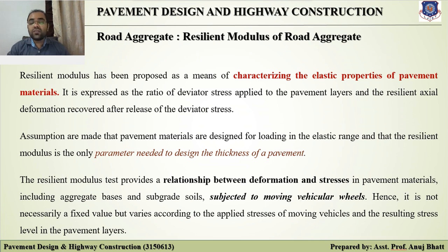For the subgrade soil we have already discussed this topic, and this is for the road aggregate bases subjected to moving vehicular wheels. Hence it is not a fixed value, but it varies according to the applied stresses of moving vehicles and the resulting stress level in the pavement layer.